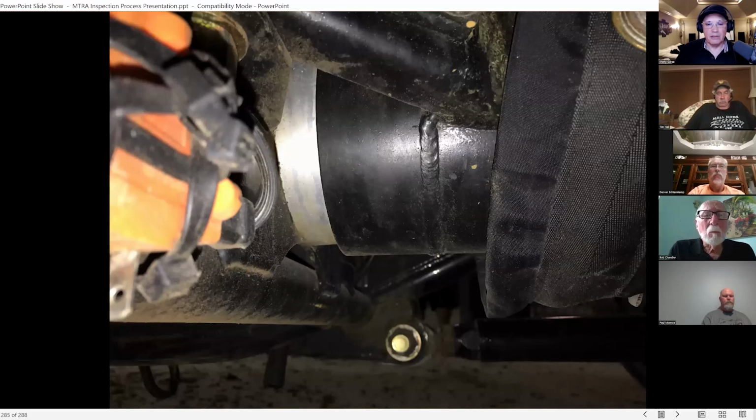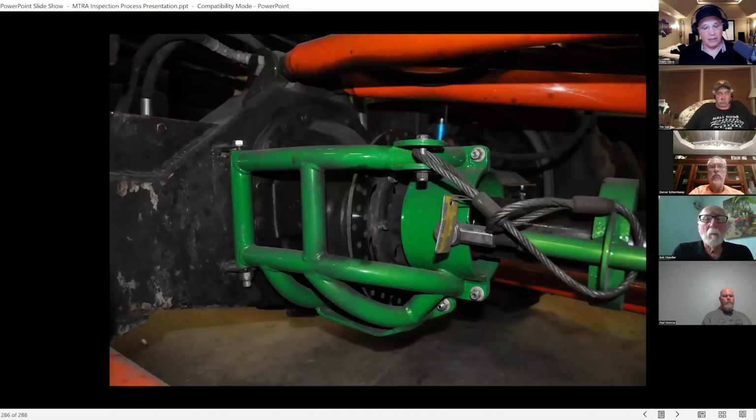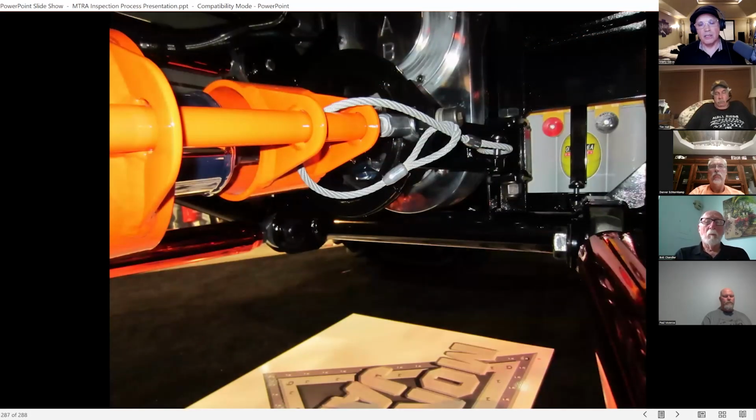The other thing was the restraints or the cables on the drive shaft loops. That's another good bit of insurance. Sometimes, because of a driveline failure, you'll have the loops get broken. They stay in one piece, but they'll break the rods or anything. The cables, if they're properly sized, will keep the loops from falling all the way to the ground, where they can get hung up on the ground and get ripped out from under.